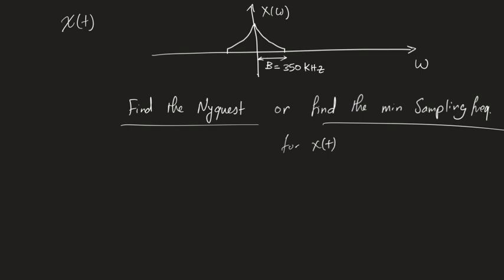Less than 2. Greater than. Yeah. Oh, okay. Greater than, right? So the sampling frequency omega s, if you write it as omega, be careful because the bandwidth is given to you in hertz, right? So you have to convert it. Or you can make things easier for yourself and you just say fs, the sampling frequency, is not equal to, sorry, Fs has to be greater than double the bandwidth B. We didn't flip it. Why do we flip it? Wn is greater than 2B, right?